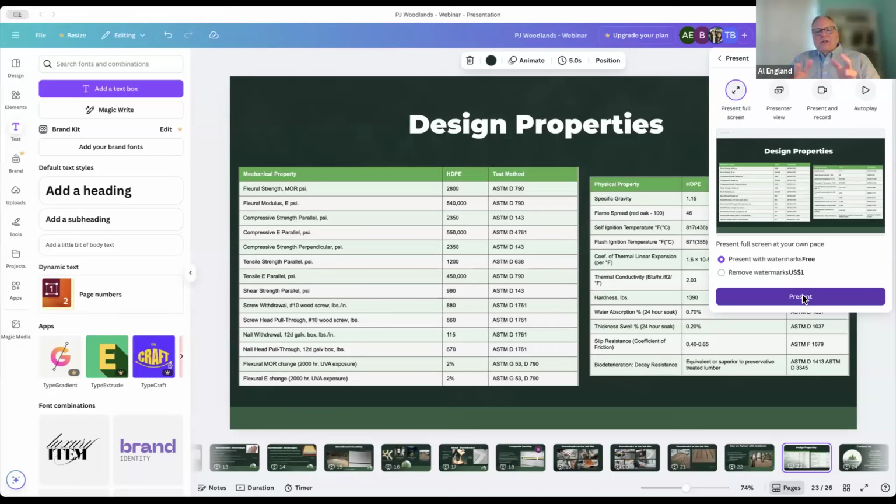As far as the trim is concerned, standard S4S dimensions, which are 3/4 by, and I'm trying to do this from memory here, 2 inch, 3.5 inch, 3.5, 4.5, 5.5, 7 1/4, 9 1/4, 11 1/4. Right.